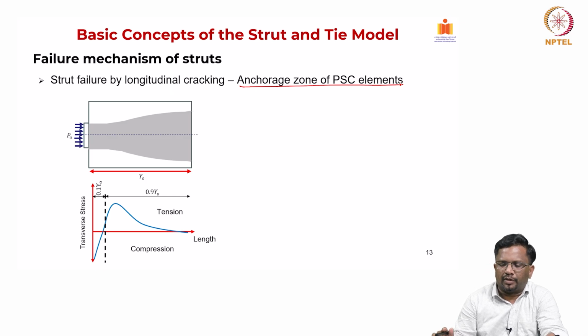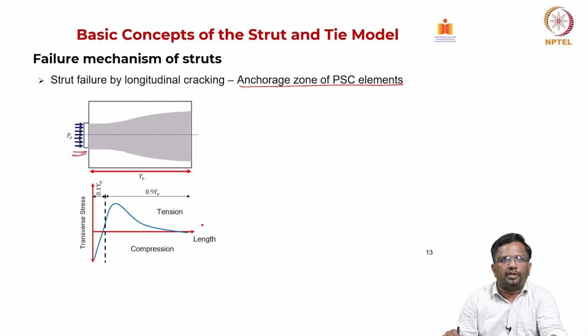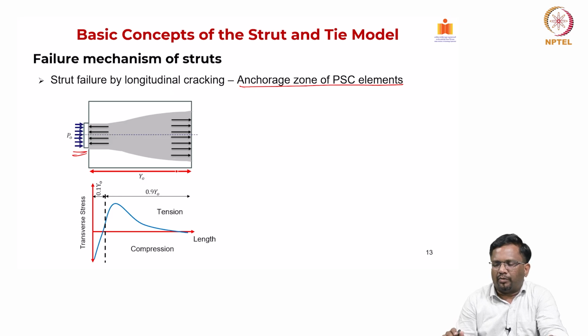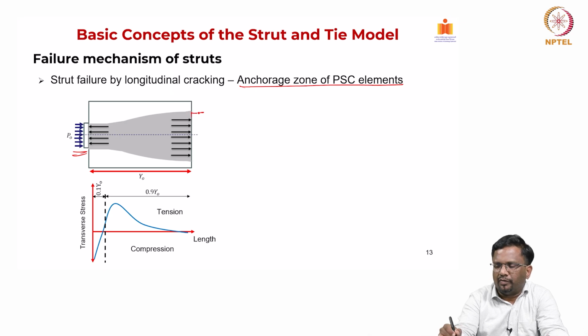We have seen that when you have such an anchorage system and you apply the pre-stress P0, for a distance equal to the depth y0 you will have this kind of stress distribution, until the stress becomes uniform, which is the region beyond which we can use Bernoulli's hypothesis.